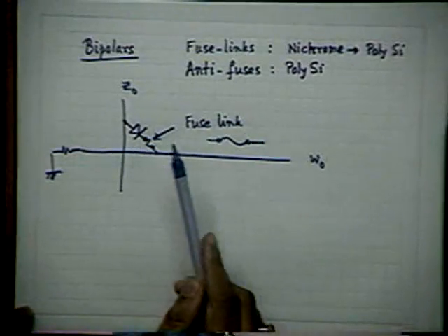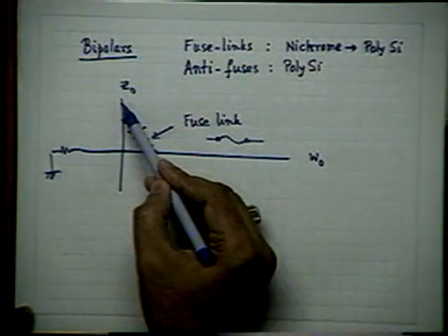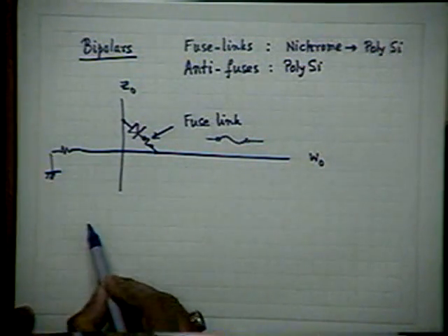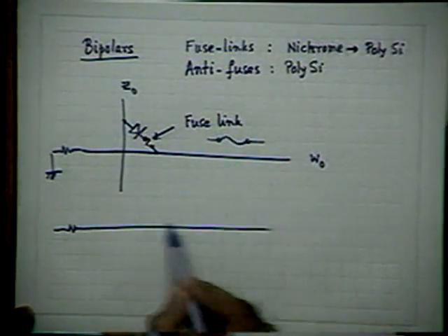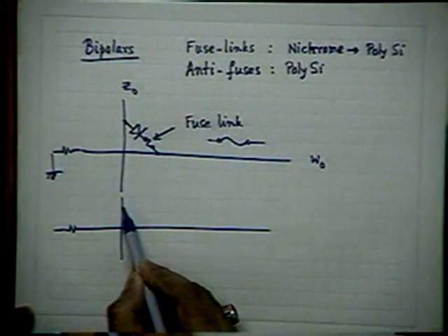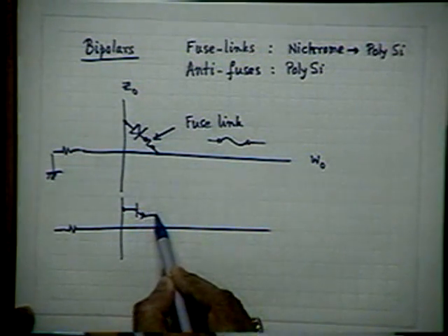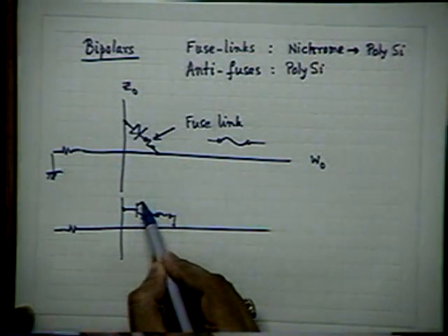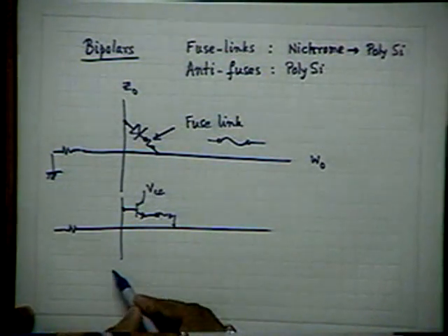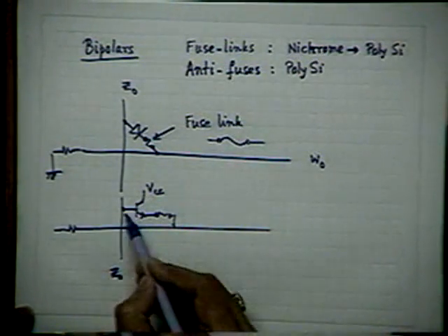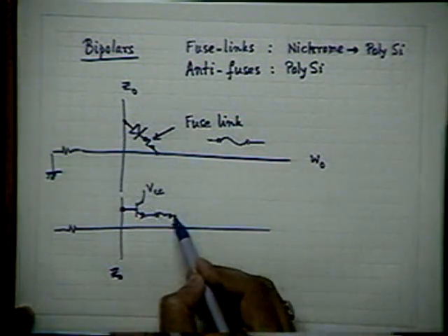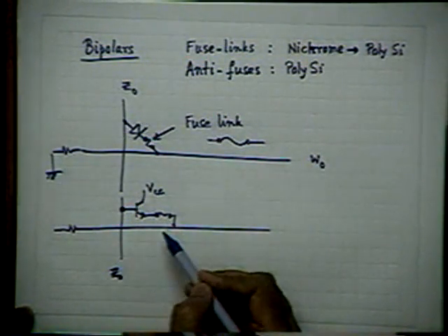And then instead of this, you could do also. But here, actually, you know that a lot of power you have to supply through Z0. What you can do, the same thing you can do otherwise by using transistors, as you have remembered. This is Z0. So apply a reasonably high bias here, gate bias, so that the current is above a certain value which fuses off this fuse.